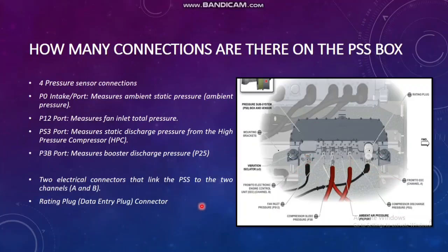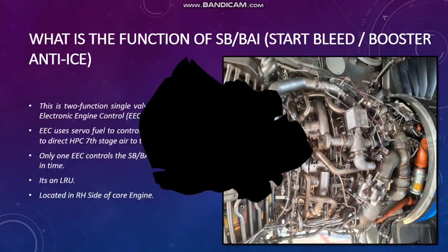Rating plug, data entry plug connector, you can see this data entry plug. In case you are replacing the PSS box, make sure the same data plug is used for the PSS box. Don't replace it with a 321 data plug or something. You have to replace only the PSS box, so we'll use the same data entry plug.